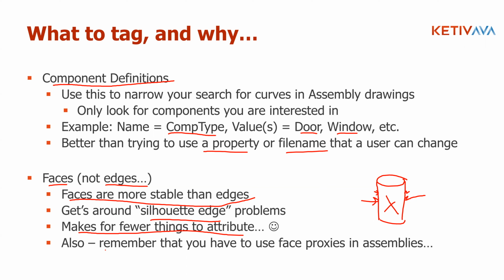Also, just one thing to remember, and we'll talk about this a little bit in the examples: when you're searching for things, you have to remember to change your faces into face proxies if you're grabbing geometry from an assembly. We won't go into great detail about that.